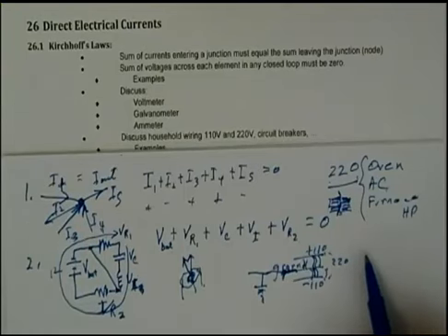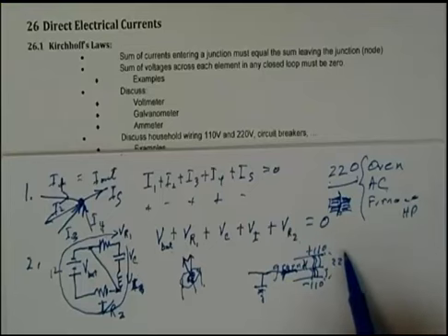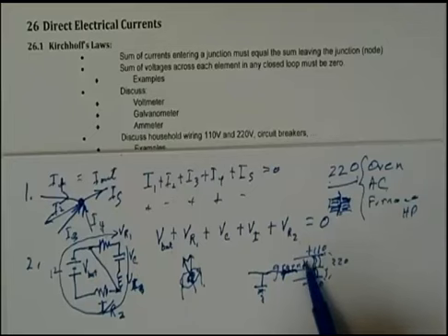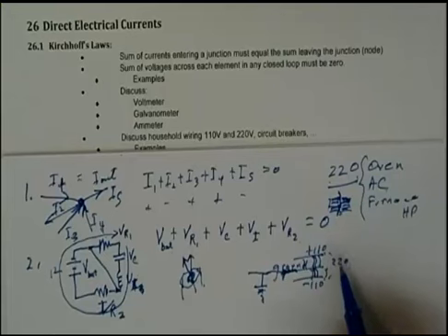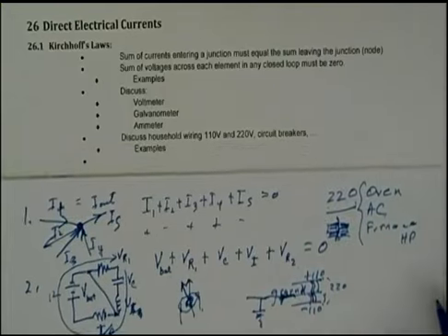That is a happy compromise, as I mentioned the other day, between having a real high voltage, which means that we don't need much wire in order to carry the current for that given power, but the voltage becomes risky in terms of arcing and electrocution. On the other hand, if we get lower voltages, the wires have to be so large, we run the risk somewhat of having a fire.